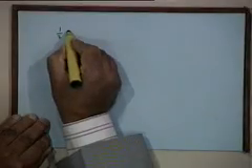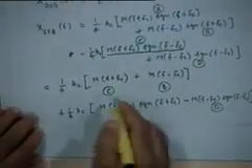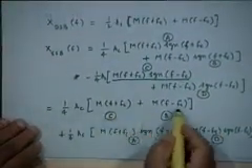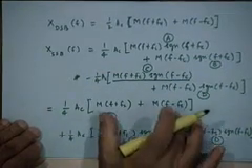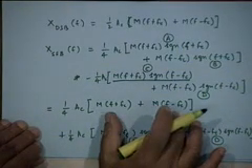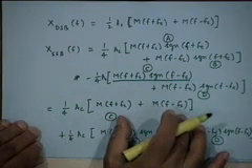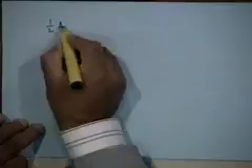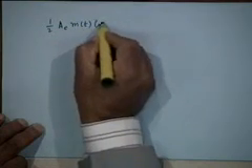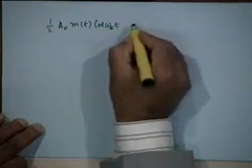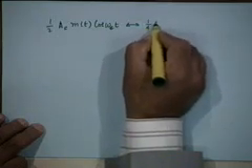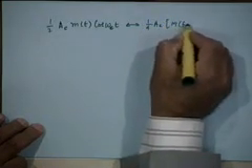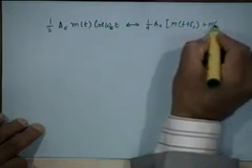Okay. So now look at the first two terms. We know that those first two terms will correspond to, can you give me the time domain expression for the sum of these two terms? What is the corresponding time function? Half AC MT cosine omega CT, right? This is a DSBSC signal, that's all. So this is half AC MT cosine omega CT, which is nothing but 1 by 4 AC in the frequency domain, MF plus FC plus MF minus FC.